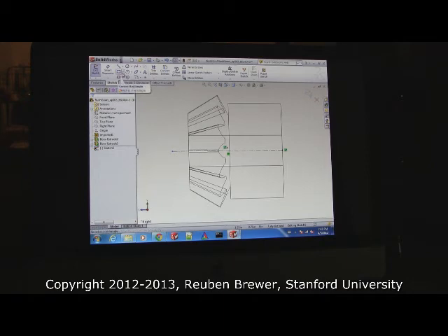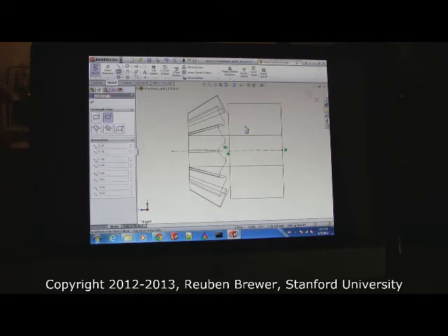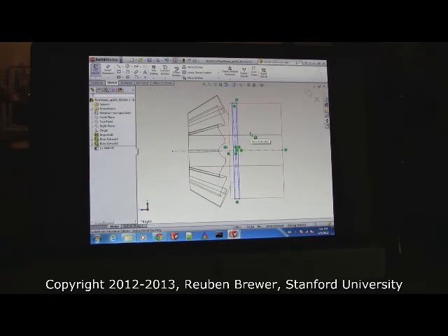Now we're going to do a rectangle. We haven't done that before. There are two types of rectangles. Ones you define by corners and ones you define by centers. Press a little arrow and select center rectangle. Everybody with me? Now click here on this line and drag the rectangle up and let the corner snap against that top line. And then press escape.